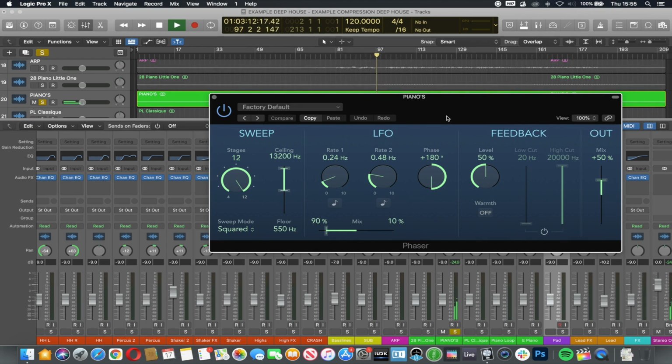So again, the signal is split into two, the normal line and the delay line. The delay line has its phase shifted, and then they are laid back on top of each other, because you have two opposite phases of the same note. A kind of a notch is created, and this is where the sound cancels itself out. If you've looked at anything to do with phase, you'll know that this is cancellation of sound. So these notches are then sweeping across the frequency range, and this is what gives us this kind of rippled effect.